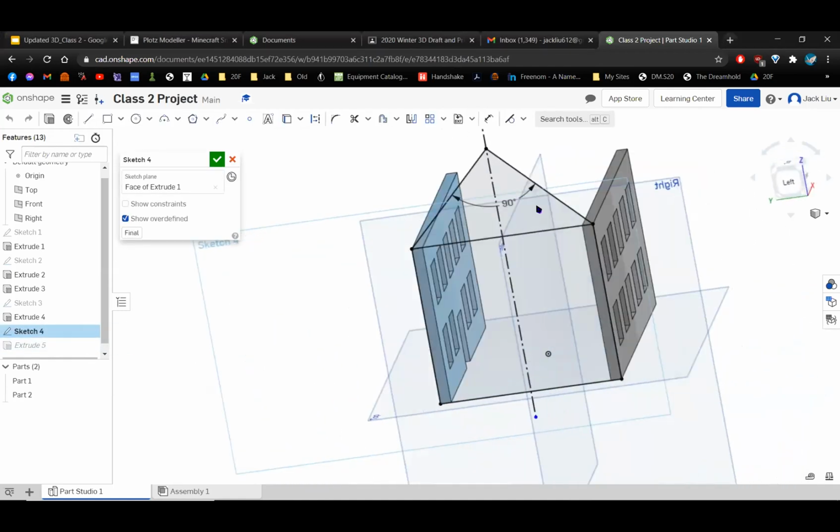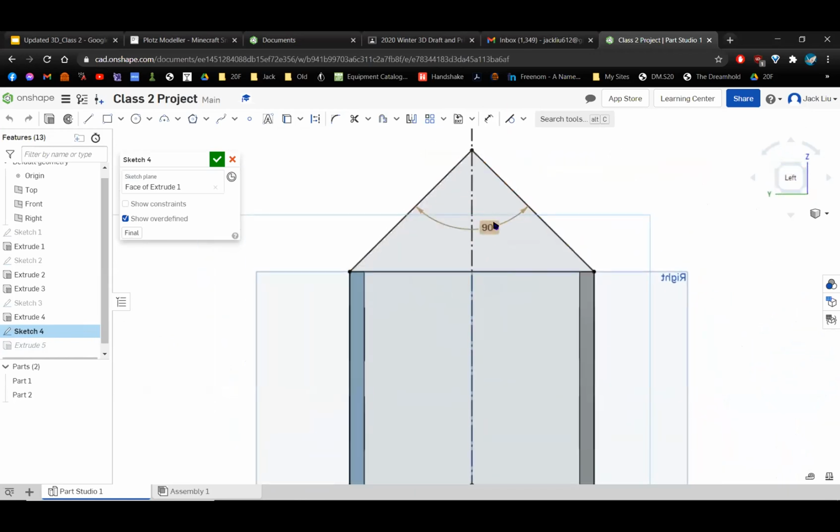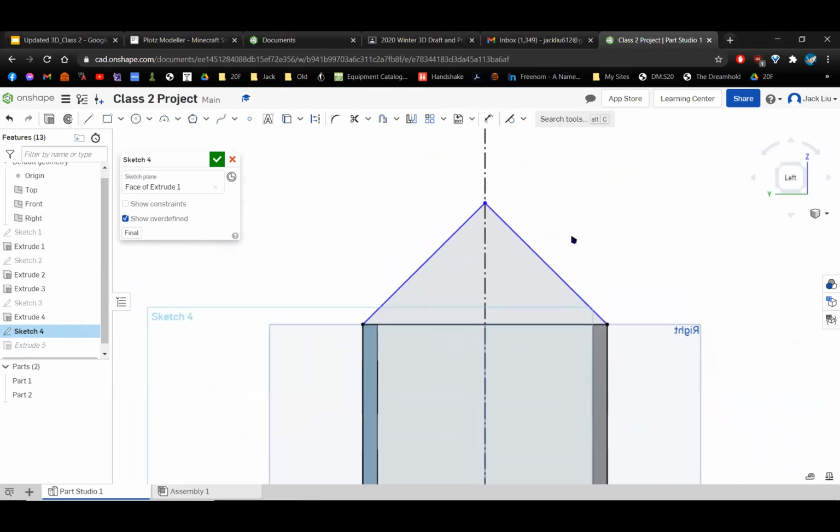In this sketch, so if we look at it here, I'm going to delete my measurement. So is this what it looks like on your screen right now? Something similar? So I'm going to move it somewhere so it's clearly not 90 right now. We hit our dimension tool. We select it, and it should be blue. We click one of our sides, right?